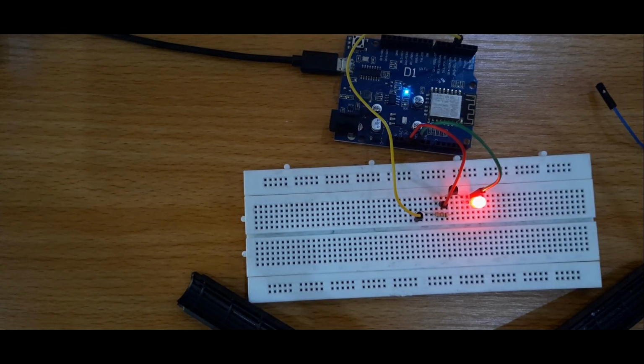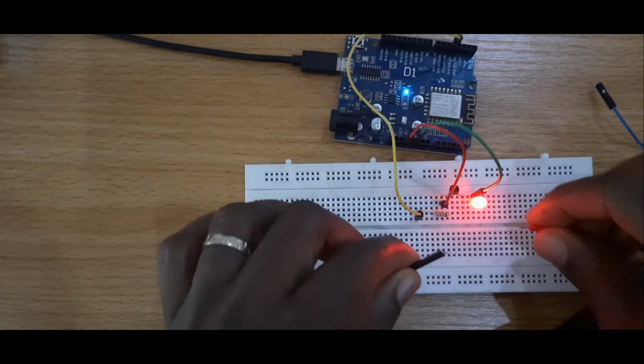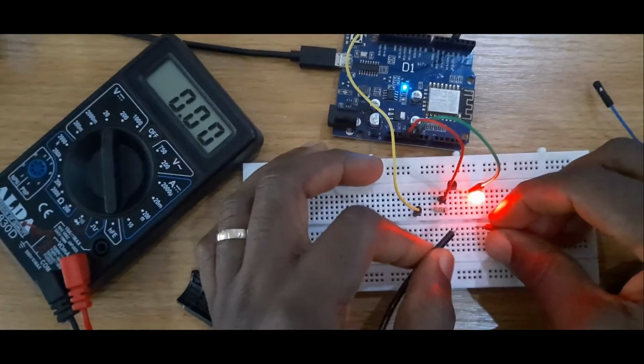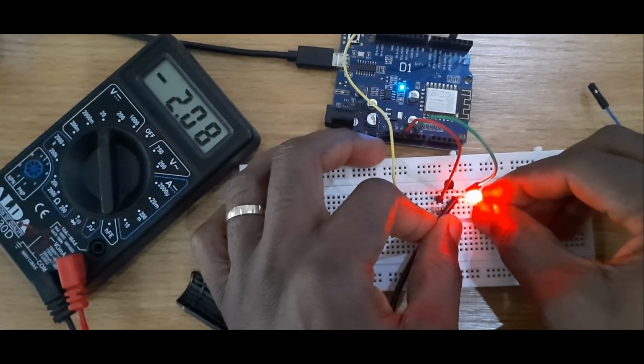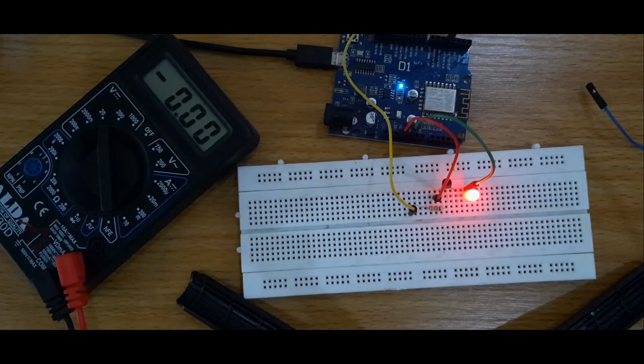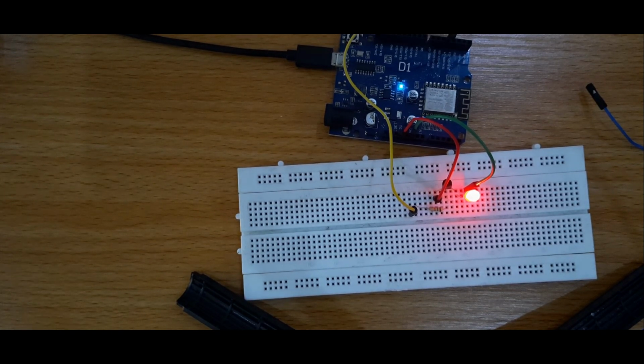Perhaps you don't know how to connect it. I might use my meter to show you how many volts it reads, so you can understand that it's very important, and it even helps you. You don't have to start calculating the resistor value for the outputs. It saves the whole circuit a lot of stress. You can see I have about 2.7 volts, which you can still play with. That's the 2.7 volts consumed by my LED. I can also work out the current, but from the last time I calculated, I got about 18 milliamps, which is perfect for me. Thank you.